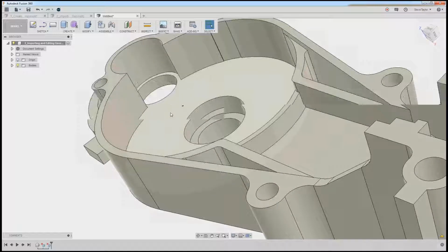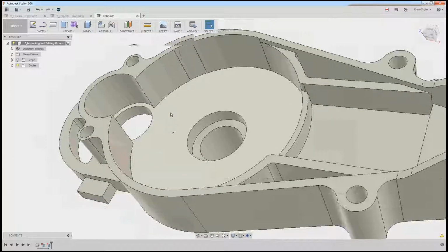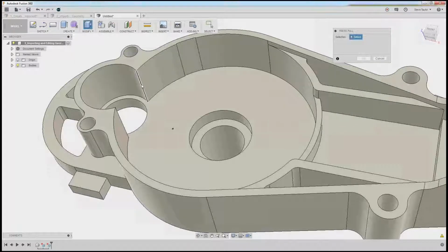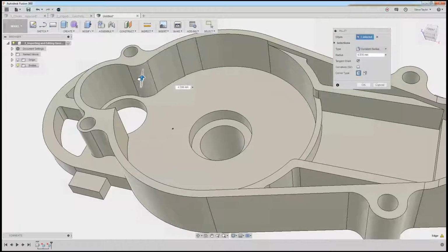So I'm actually now modifying this existing model. If I was to right click, press pull, click on that edge, you'll notice I can actually change the size of that now, and it's actually putting it in as a fillet. I'm not so sure if it would have recognized it as a fillet initially, but now that I've deleted it, I'm putting it in a fillet. It's also making it tangential, because as I'm doing it, it's making sure that that is a tangential fillet to that side.